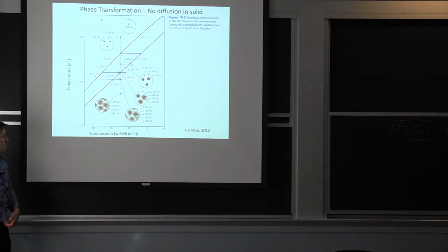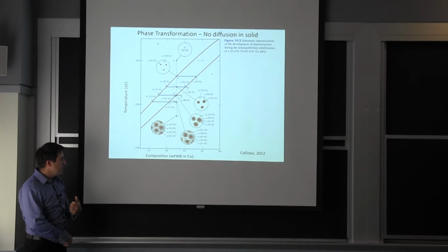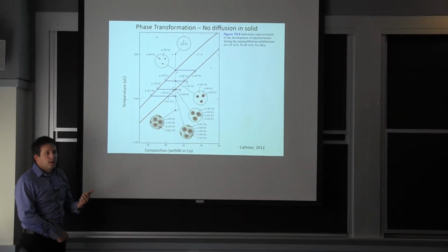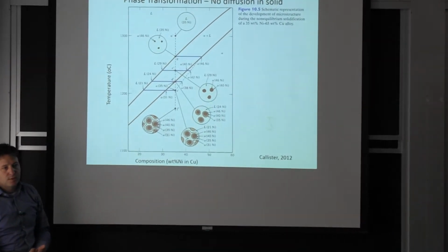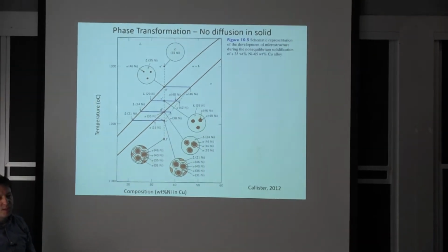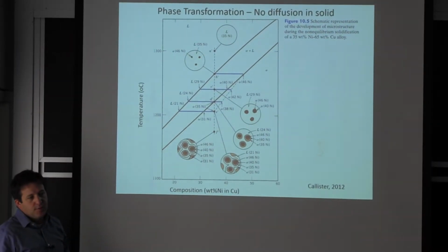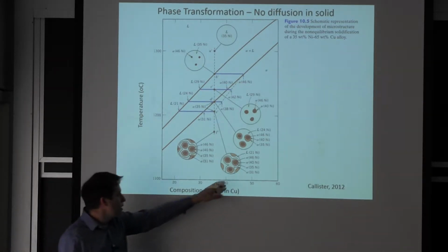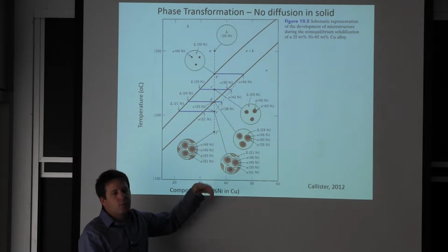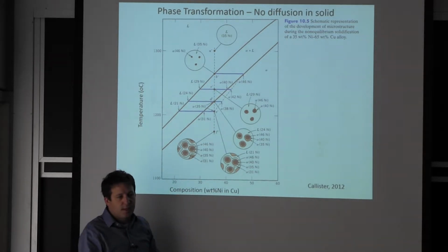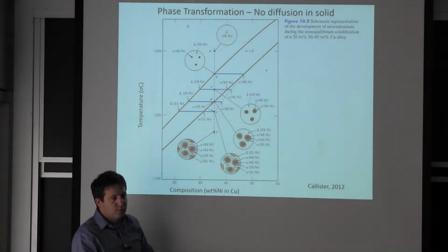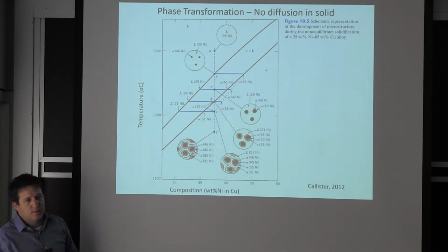And it's really what happens with all the cast iron and all the steels. If you're going at a reasonable pace, you're going to have all that change and segregation. You're going to have a different composition where you're nucleated, with that high temperature equilibrium condition, and then at lower temperature, you're left with the extra alloying element that couldn't fit in, or the system didn't want in the solid to begin with.